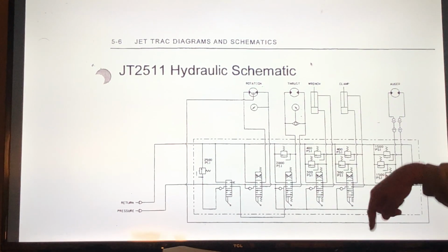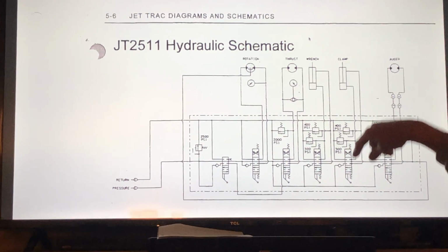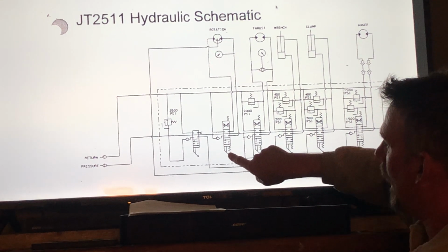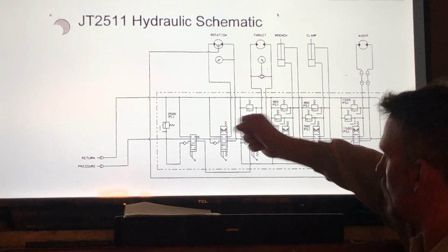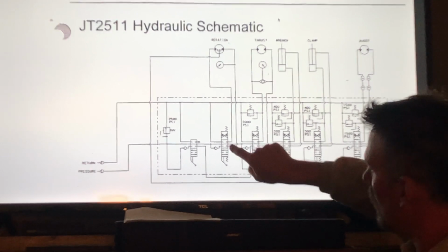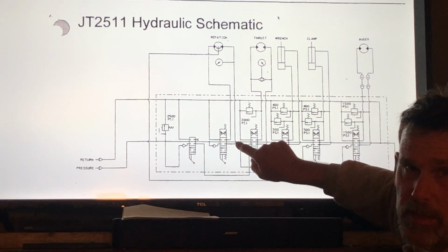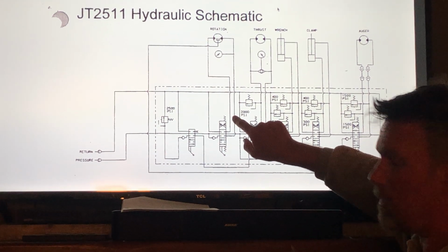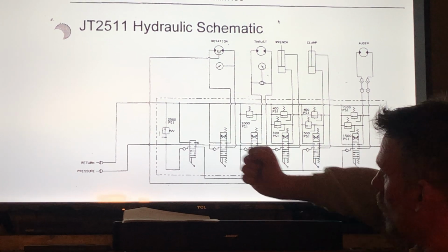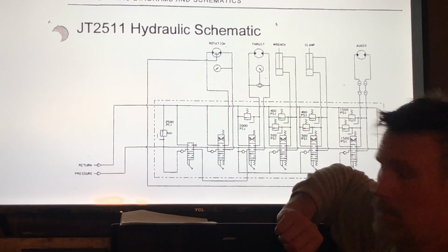Okay, so forget about what these do. Let's go back to talking about the tractor. Let's look here. Okay, here's our handle that I was talking about, and this is what I would pull if I wanted to lift it further. So out here, this is the work port that's holding that bucket up in the air with all the gravel in it. And we said that it was at 2000 PSI trapped in there, holding that bucket full of gravel up. Okay? Now, when I pulled on the lever, this main line was at 0.